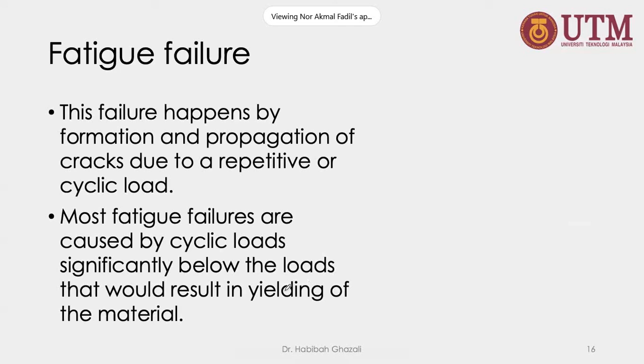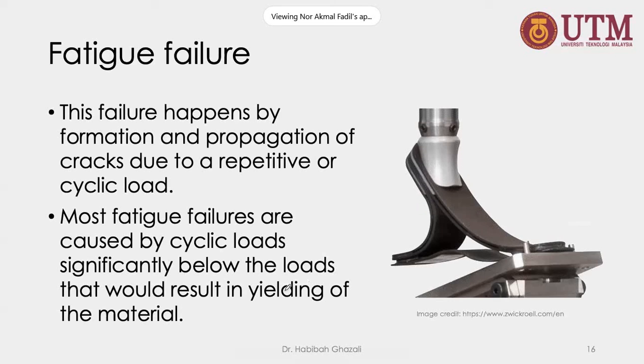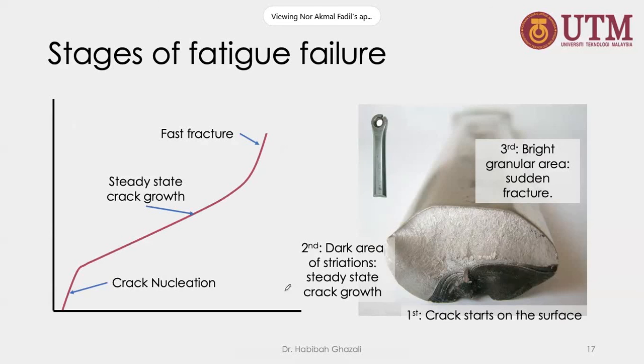Even though it can support the load at that limit, and you put a safety factor, half of the actual load that gives plastic deformation, still another failure may occur, which is fatigue. Like a suspension of a bridge or your car suspension, even though the load is very much lower, it can still cause failure. We call it fatigue failure.